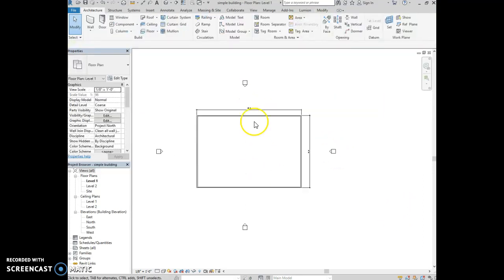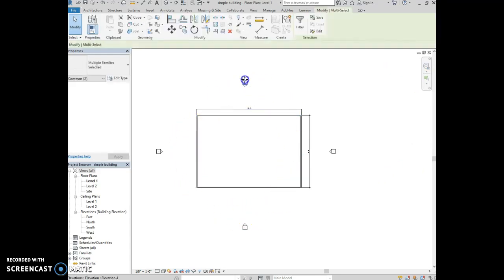So again, make sure that when you're drawing, you're always drawing between these little markers here. These are elevation markers. They're used so that the program can understand where you want to see your exterior elevations, okay? So if you draw outside of them, you won't have any exterior elevations, so you always draw within them. They can be moved if your building gets too close to them. You can move them up and down, okay? But always draw in between them.